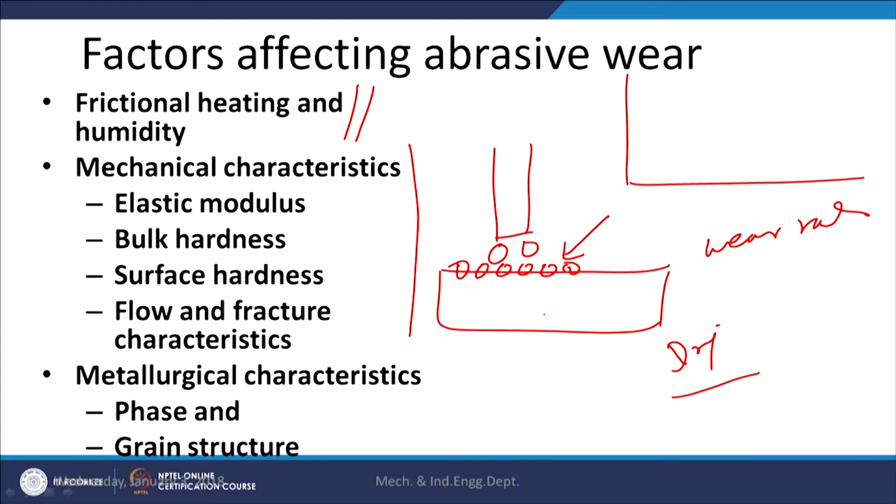On the other hand, if the frictional heating is too much, then it will lead to a rise in temperature of the surface of the workpiece, which will soften the workpiece material and increase the indentation depth by the abrasives, which in turn will increase the abrasive wear of the material.